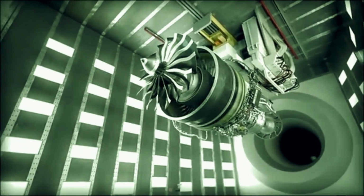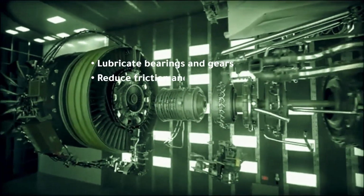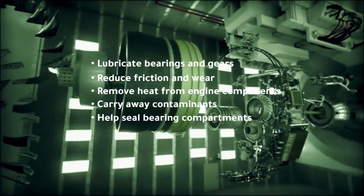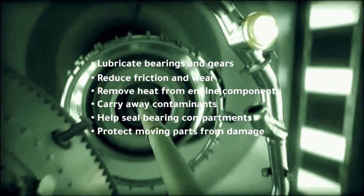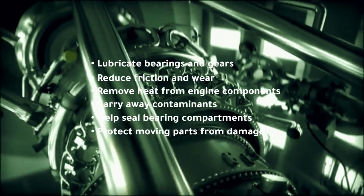A turbine engine lubrication system has several important jobs. It must lubricate bearings and gears, reduce friction and wear, remove heat from engine components, carry away contaminants, help seal bearing compartments, and protect moving parts from damage. Most turbine engines use a dry-sump lubrication system because it can carry more oil and control oil temperature more effectively.